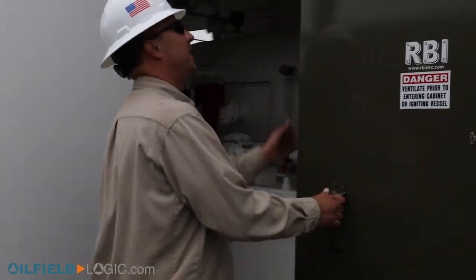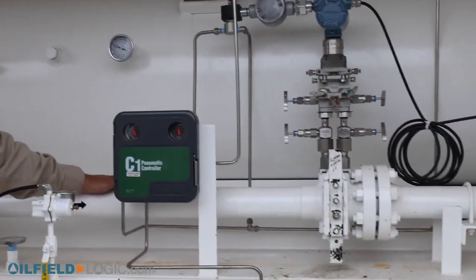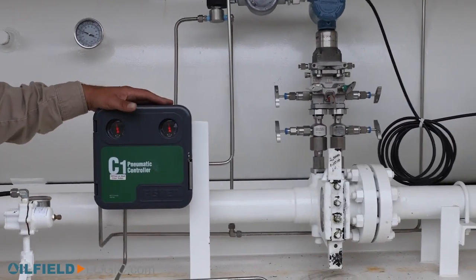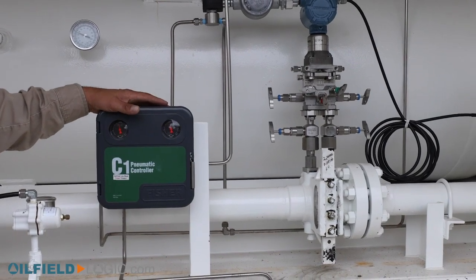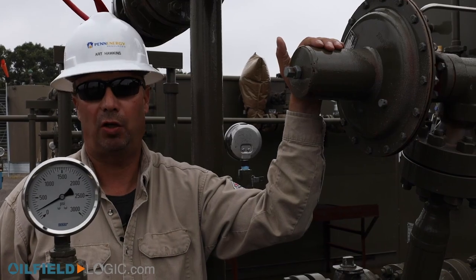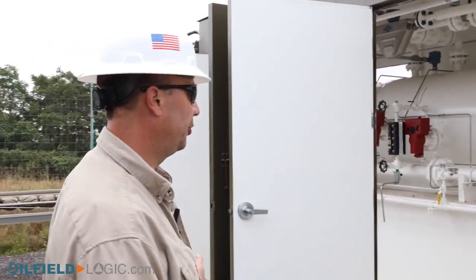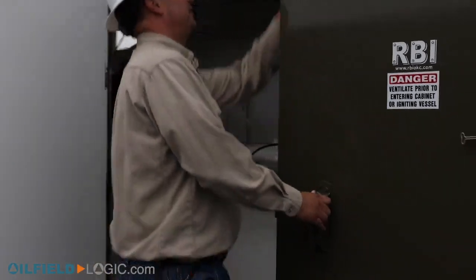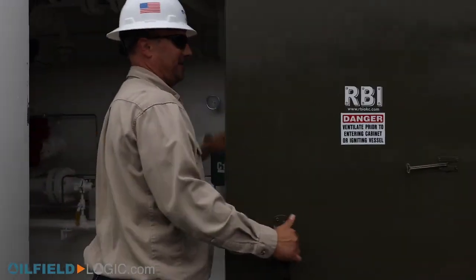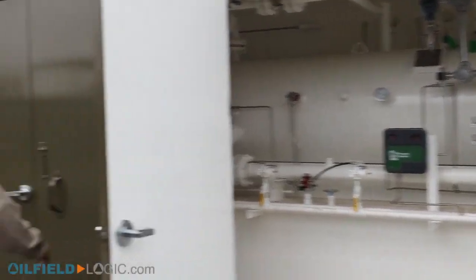As we go through the production unit here, I'll show you some devices that we have set that will monitor pressure. As pressure gets above certain set points, this will start to trim back this valve and throttle back our flow. This is a single unit that we've gotten from RBI. We really do like the design from an operator perspective. Very easy to access mechanical parts to be able to work on things, maintain.